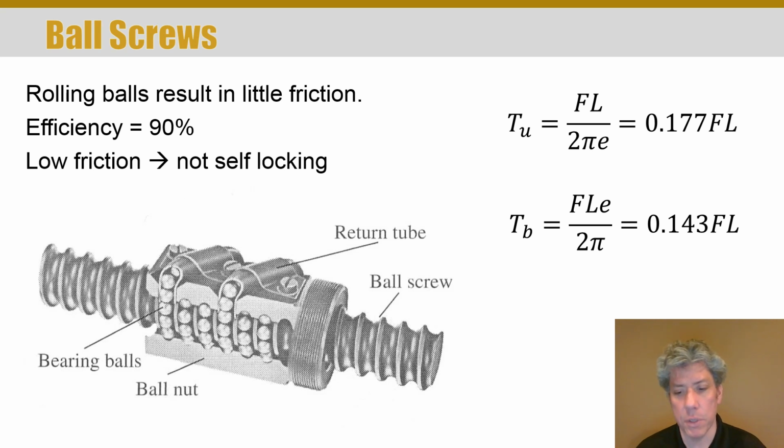I know when I first started working for Amatrol, my colleagues in the department were redesigning one of Amatrol's robots. It was called a SCARA design, S-C-A-R-A, I believe. Basically that meant it had two horizontal axes, so it could go anywhere in a 2D plane, but to get the up and down motion, the Z-axis motion, it used a ball screw for the end effector. You could use a motor to turn the ball screw and raise and lower an end effector pretty easily.